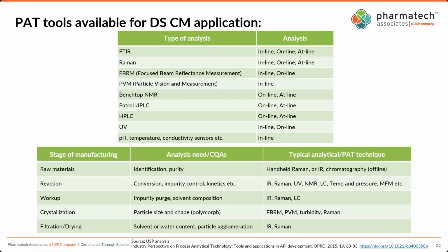Coming back to the PAT tools, they include many measurements and instruments such as MIR, near IR, Raman, low-field NMR, etc. But it is important to remember that just as there is no single offline analytical tool that meets the process development needs of a product, there is no one PAT or in situ analytical tool that will work for all applications.